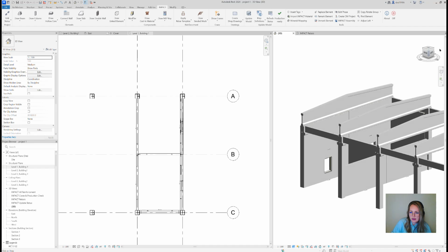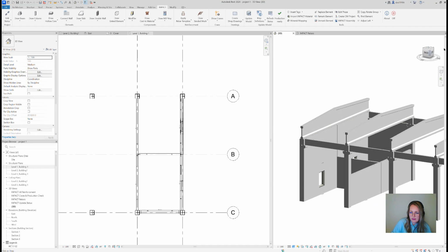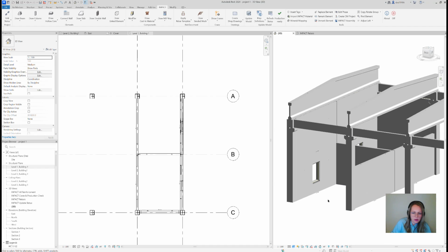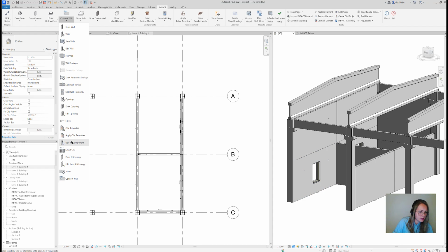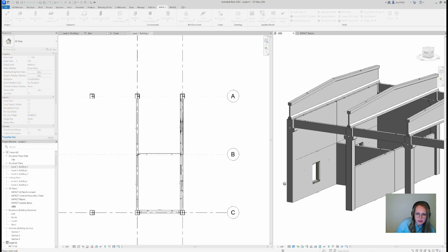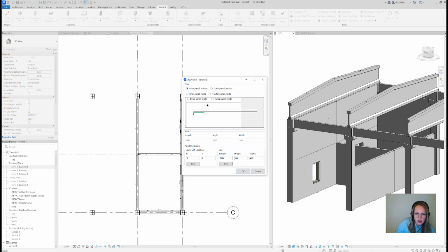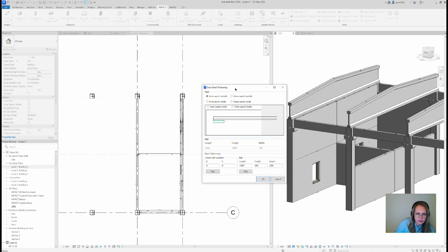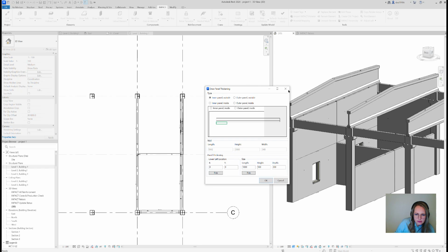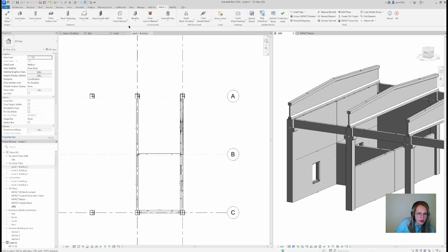The panel thickening is used in many situations when we talk about precast, but I want to draw it now for supporting the slabs. So if you go to the wall folding menu, you can say panel thickening, select the wall, and here you can see that you can either select one or two.